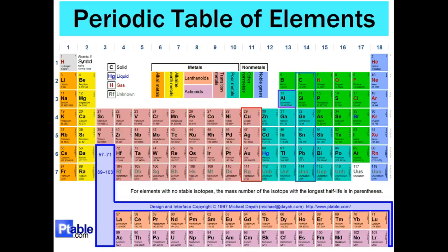It was real neat because you could trim them by taking a file. You just take a little V-neck file and you could set that resistance to about anything you wanted. We used to do that on some of the transmitters over at the structure mill, where the cranes opened the doors on the furnaces. Those were RF, and the RF frequencies got to be perfect, and that's the way we used to trim those frequencies. We'd take those resistors and then coat them with insulating paint.